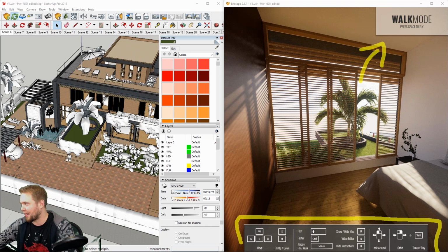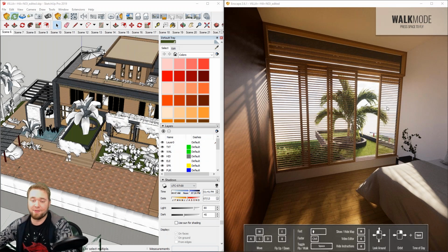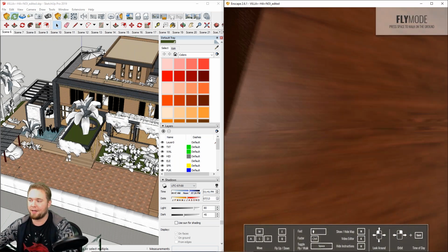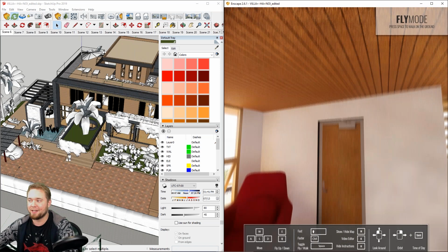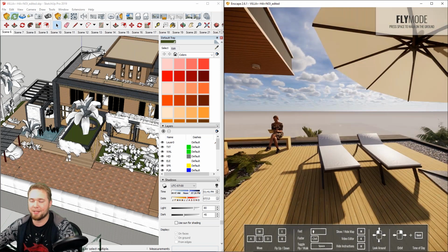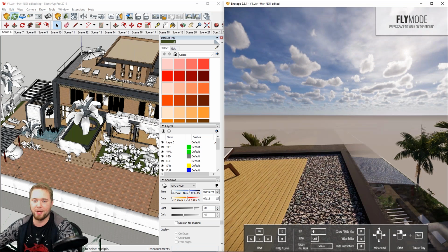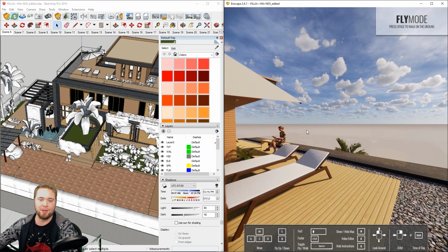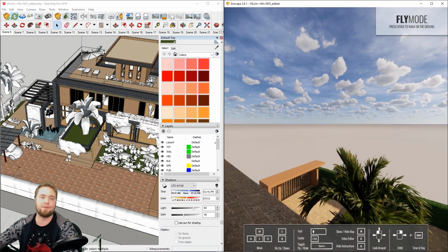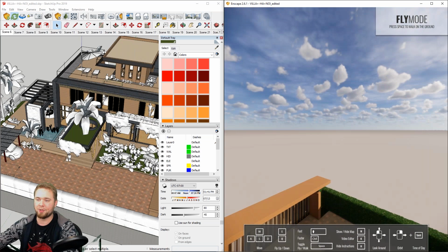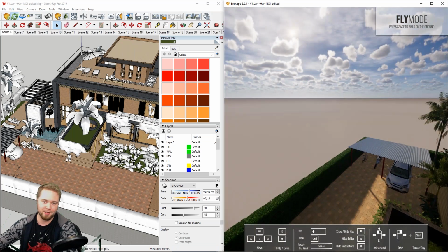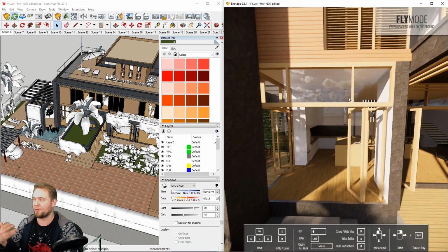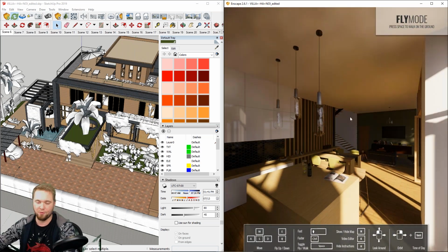Okay, so that's like the basics of navigation. If you're new to all of this, I will have a useful tip in a second. But if you want to get into WASD movement and using your mouse this way to navigate in Enscape, what I find is a good way to start with is just pressing down the W key to move forwards and the left mouse button to be then able to move the mouse to steer what direction to move into. So that way you can get a good first grip on 3D movement with WASD.